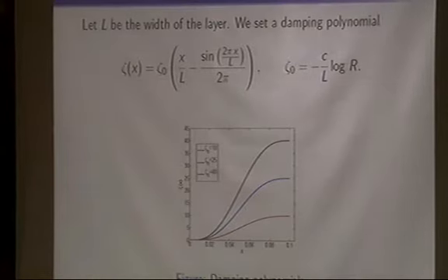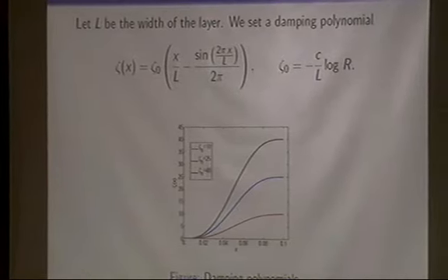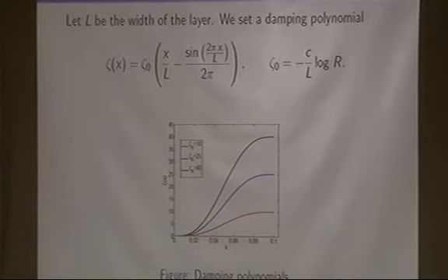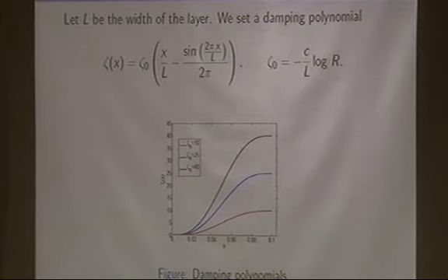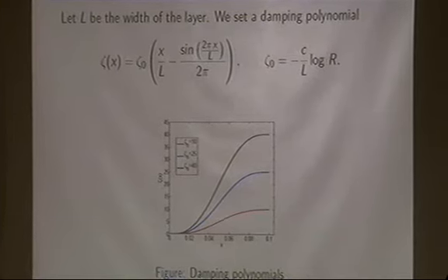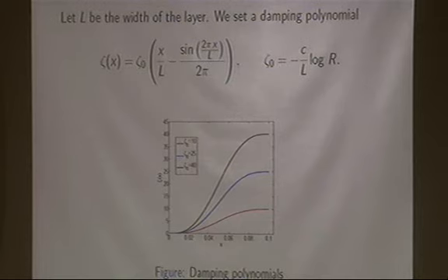Also for this new coordinate system, we need to have damping polynomials. As per your question, we don't have any discontinuity. So continuously, you can put this kind of polynomial. That means in the computational domain this polynomial is 0, right? So it is non-zero just in the PML layers.